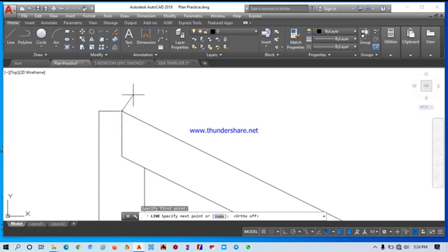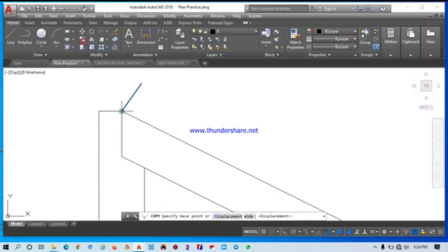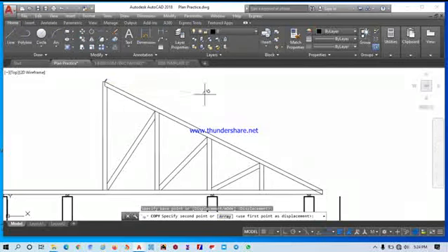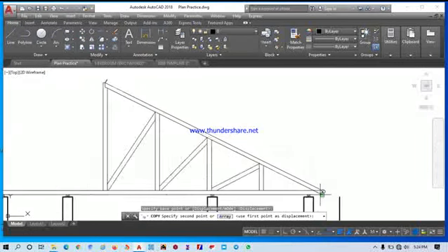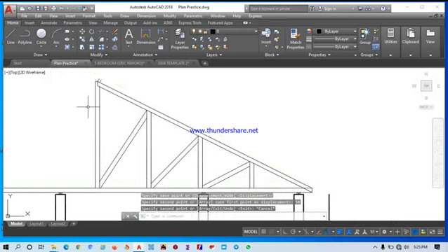So that means here we'll be having 75 mm by, let me just offset another, for precision, 50 rather. The thickness will be 50, so let me offset another 50. Offset is not making sense, so let me just use copy. I'll use copy and use that as my reference point. I need precision, I want it to be perfect. So I'm clicking on this line, and if you follow this line, my copy will follow this line. So 50 mm, that's the thickness. Can you see? It's there.